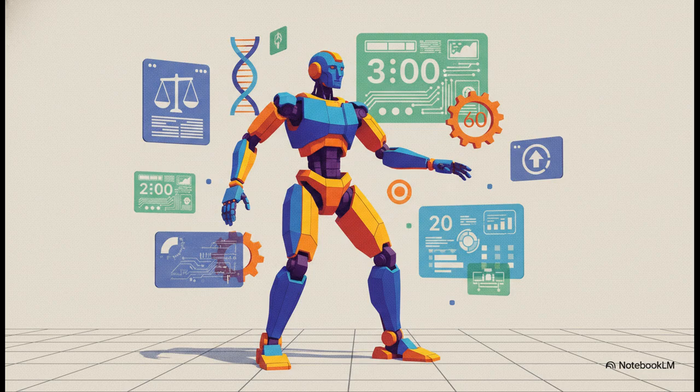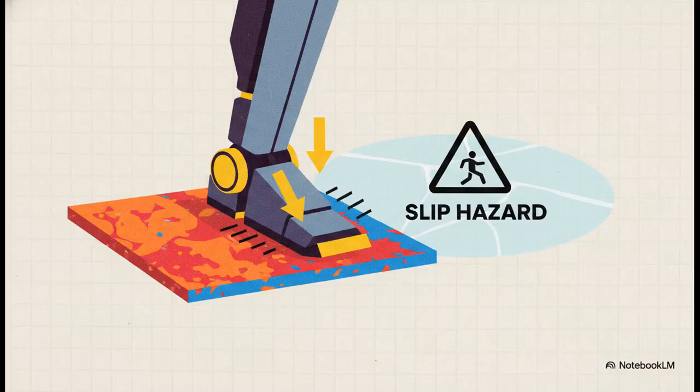These high iteration parameters, that is our mathematical safety net. It's what keeps our virtual robot firmly planted while it shifts its weight around. But hey, internal posture isn't the whole story, right? We also have to account for the ground right beneath the robot. By optimizing the material properties in our simulation, we create high-friction surfaces beneath the robot's feet. This material optimization is what directly prevents the robot from slipping during those intricate pose adjustments, because let's be real, a mathematically perfect pose means absolutely nothing if your virtual floor is made of ice.